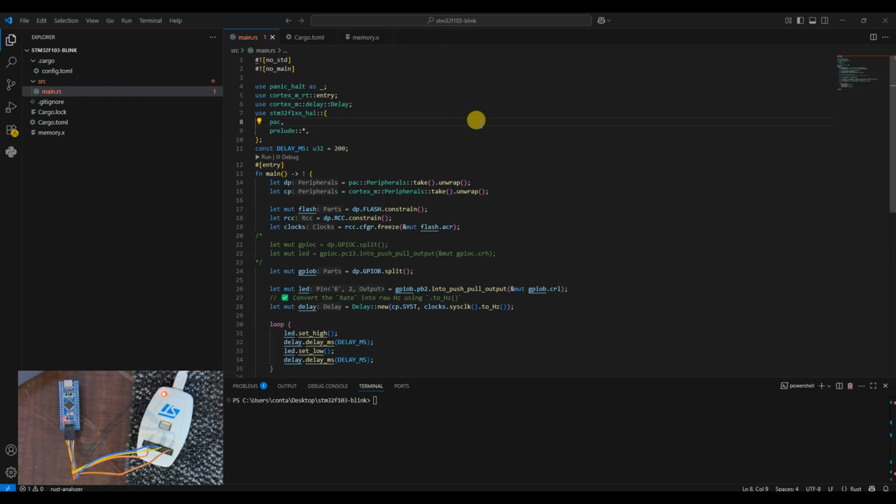As we know, we need some startup code for each and every processor, so this handles that startup code, initializing the microcontroller's RAM, setting up the stack pointer, and initializing static variables. So this replaces the standard main function in the embedded context. That's why it is needed.